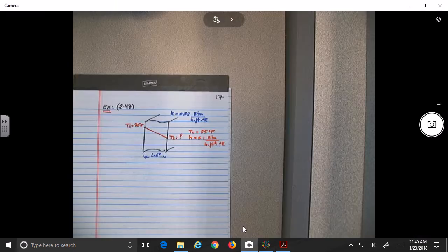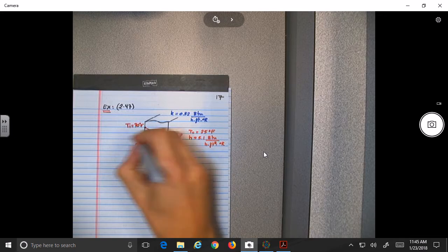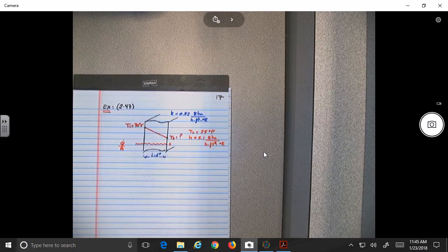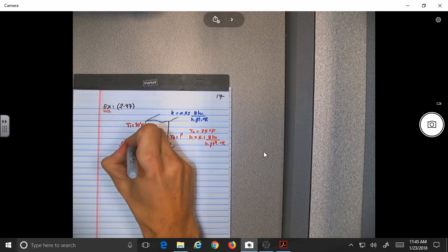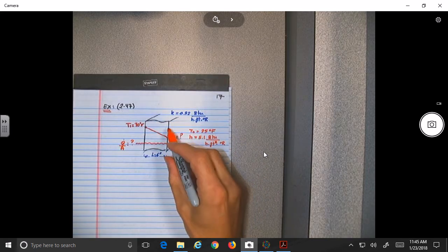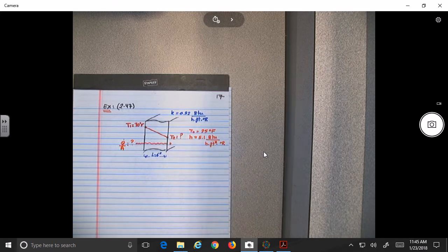Yeah. So this is what I've done. And now they ask you to find the heat transfer going through the wall from hot to cold. The units we were trying to use is per feet square, so it will be per unit area, no? So these are the two things we need to find: T2, the temperature of the wall on the cold side, and the heat transfer rate.